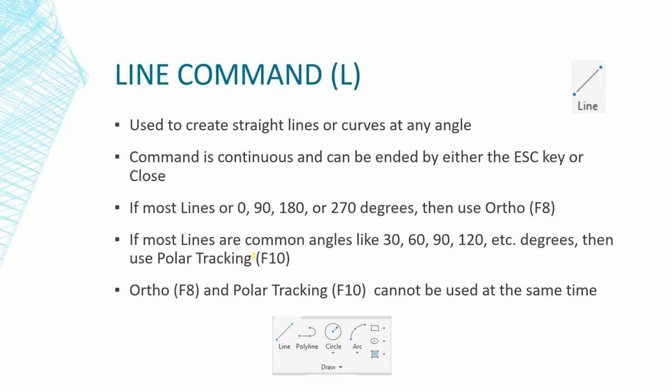Some of the things we looked at in the line command is we learned how to create some straight lines and some lines at angles. The reason why you see the word curve here, some programs will call it curves, but in AutoCAD, we're going to call them lines. We took a look at the command in AutoCAD is continuous until we either end that command by hitting the escape key or using the close function inside of it.